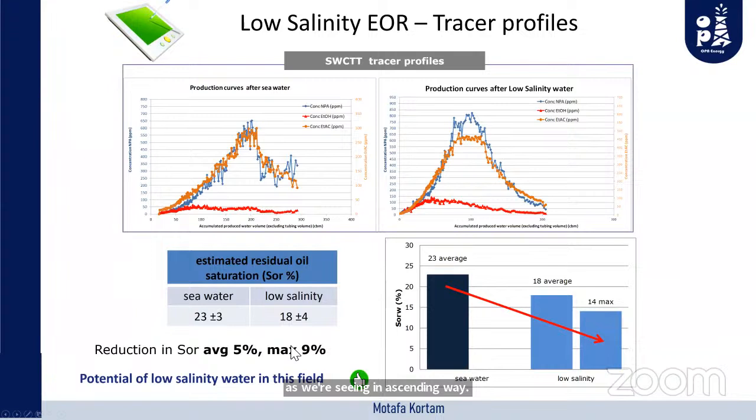So you will be able to figure out and rank the effect on the residual oil. In case, for example, the seawater provides the same as the low salinity, then at that moment you can conclude that the microscopic efficiency will not change greatly with the chemical EOR application. So you will understand, and you save the time and the money for the pilot test.